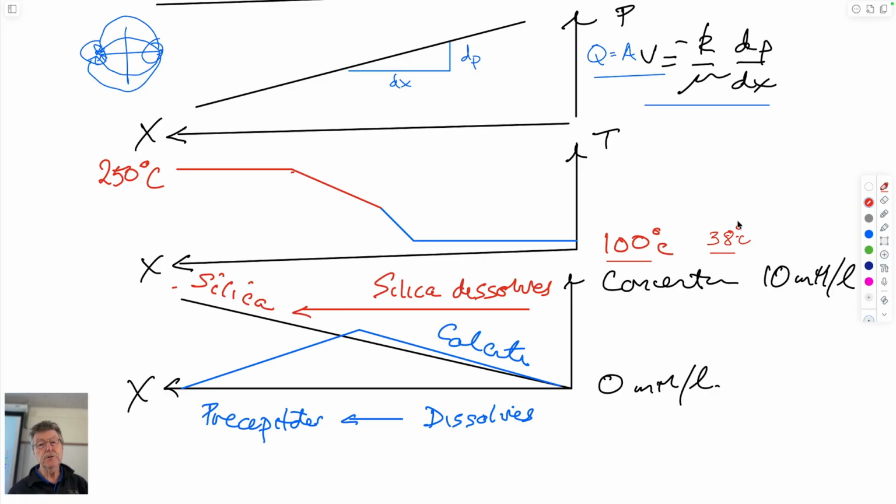So in a closed system, you can run that through a turbine and generate electricity. So you have to have a phase change to run a turbine. If it's water being flashed to steam, it has to be 100 degrees centigrade at atmospheric pressure. But if you use a different closed system with a lower boiling point liquid, then you can also run that through a so-called binary plant.